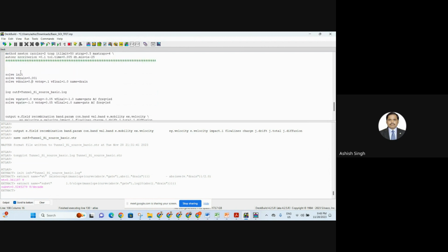So here you can change. In your CMOS device, like MOSFET or TFET, you have two main voltages. Which ones? Drain voltage and gate voltage. Mostly your source voltage is connected with the body voltage. Why is the source voltage connected to the body? For reduction of the body effect. So no need to define your source voltage here because the source voltage is common. Common means connected. So only define drain voltage and gate voltage.